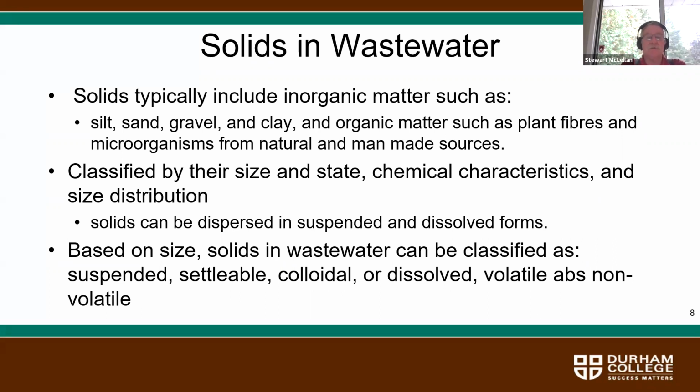Based on size, solids in water can be classified as suspended, settleable, colloidal, or dissolved, and also as volatile or non-volatile. So those are really the different classifications of these solids. If you take a jar and add some soil to it and shake it, the settleable solids will drop to the bottom of that jar within minutes of you stopping agitating it.